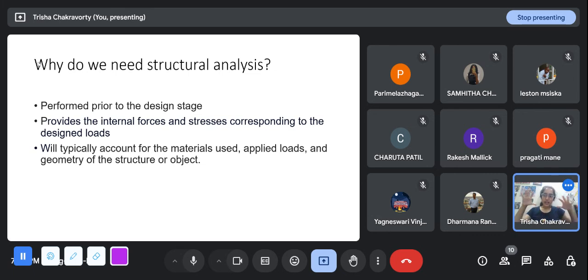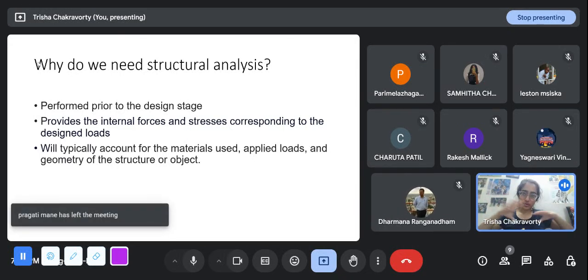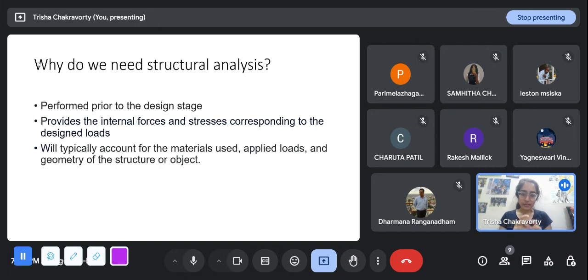So I know the live load that I have to take, I know the dead load that I have to take. And then considering the region it is built in and the soil criteria, we have some earthquake loadings and wind loading patterns that we have to take. So these are the broad force loading patterns that we have. But now this cannot directly be used in design, because when we design, we have to do it element wise.